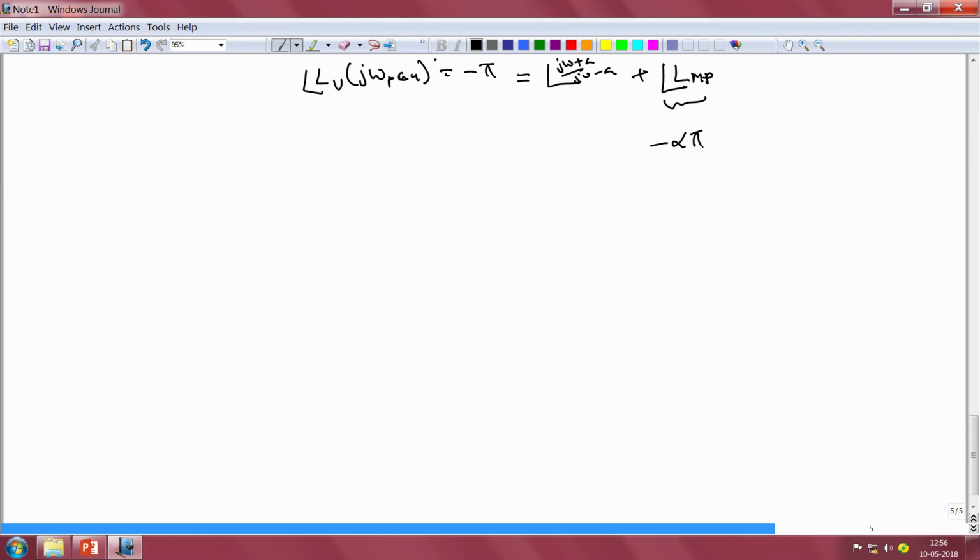So, that is going to be the phase lag of the minimum phase part of the loop gain, and the Blaschke product of course will have a phase of minus pi plus 2 tan inverse of omega by A, and that is going to be equal to minus pi at the lower phase crossover frequency. So, from this equation we note that the lower phase crossover frequency, omega Pcl, is given by omega Pcl equal to A times tan of alpha pi by 2.